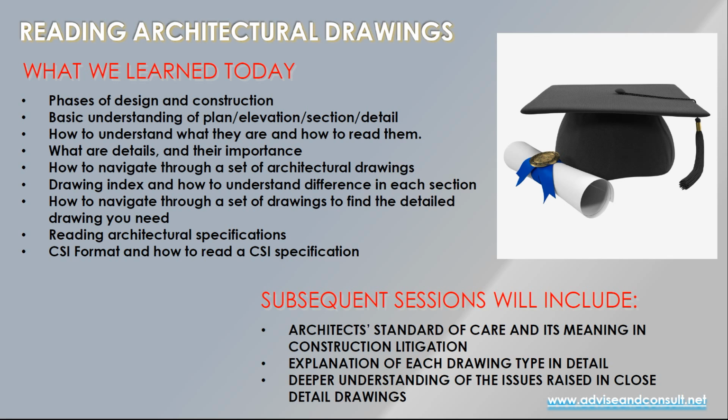What that requires is a lot of knowledge about what all of the technical representations of the various building materials are. So you need to know what insulation looks like in an architect's detail, or what building paper, or what roofing material, or vinyl tile, what any of those materials actually look like, and what the rendering convention is, so that you can identify them.